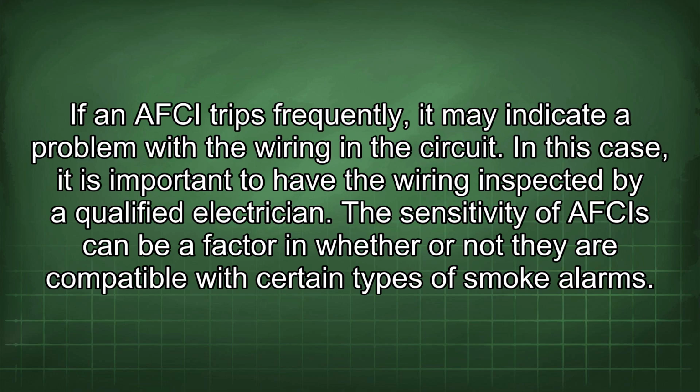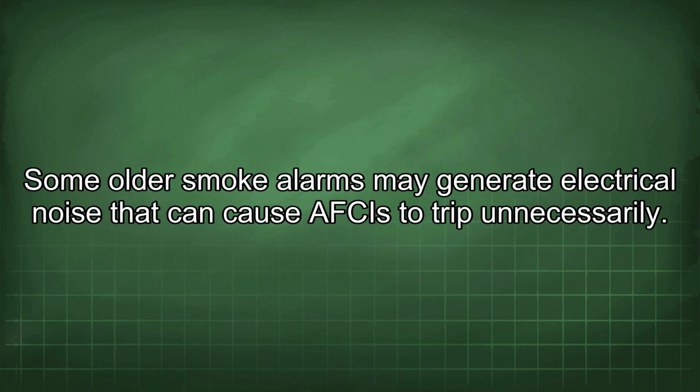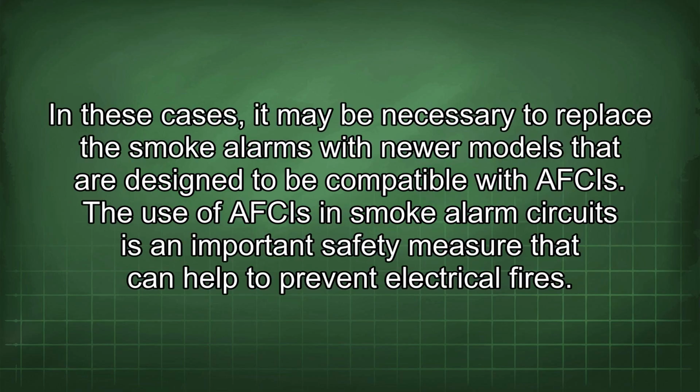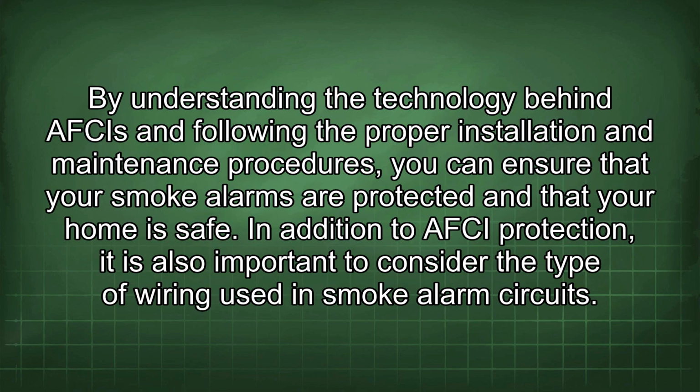The sensitivity of AFCIs can be a factor in whether or not they are compatible with certain types of smoke alarms. Some older smoke alarms may generate electrical noise that can cause AFCIs to trip unnecessarily. In these cases, it may be necessary to replace the smoke alarms with newer models that are designed to be compatible with AFCIs. The use of AFCIs in smoke alarm circuits is an important safety measure that can help to prevent electrical fires. By understanding the technology behind AFCIs and following the proper installation and maintenance procedures, you can ensure that your smoke alarms are protected and that your home is safe.